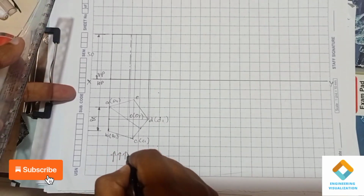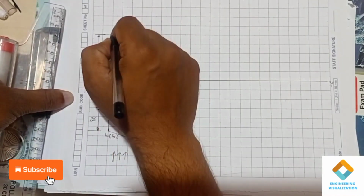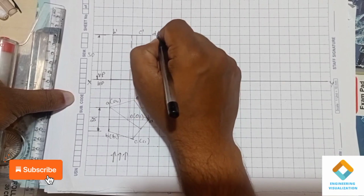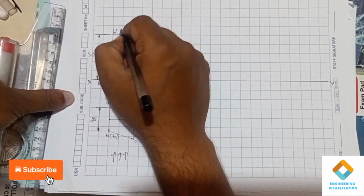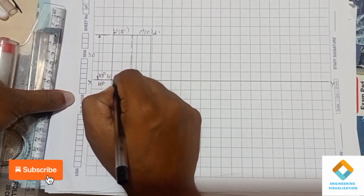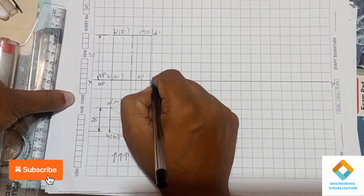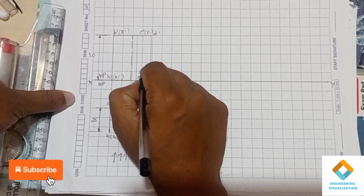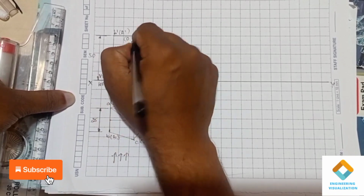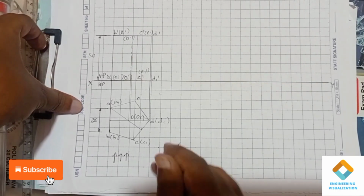From the front view, B dash, C dash and D dash are visible, A and E dash are not visible. So B dash visible here, C dash visible, D dash visible, E dash and A dash in bracket. In the same way for the bottom face, B1 dash and A1 dash not visible, C1 dash visible, D1 dash visible and E1 dash not visible. In the same way, axis center O1 dash and O dash not visible. So now we are done with the first position.